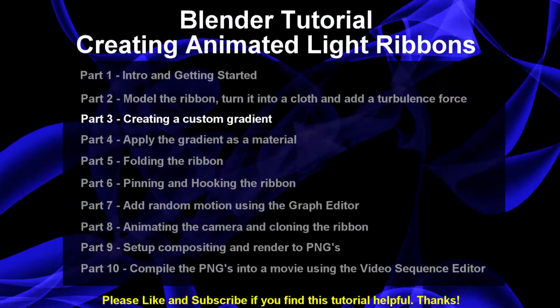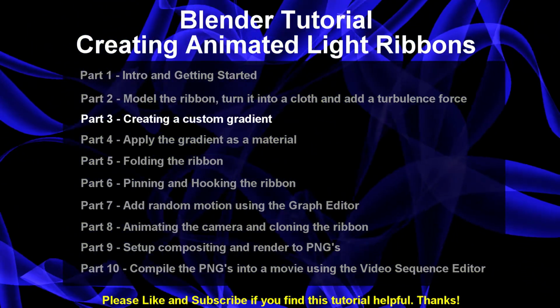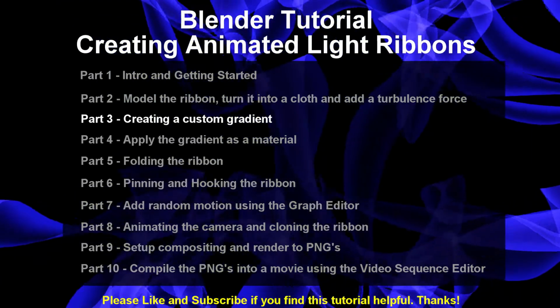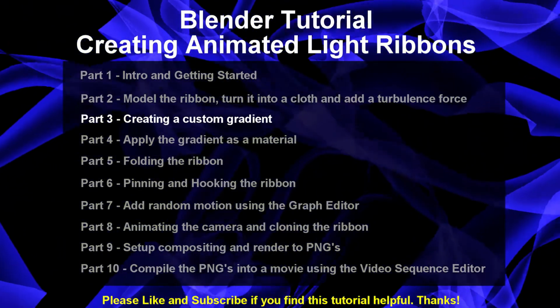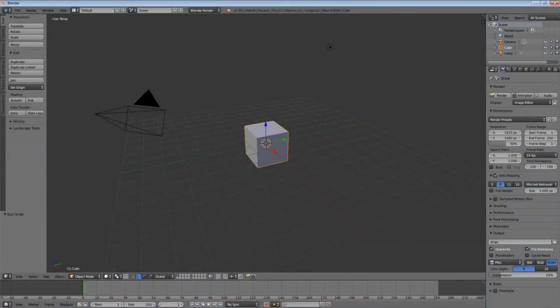Hello and welcome to part 3 on how to create animated light ribbons using Blender. In this part we're going to create our own gradient texture to apply to our ribbon. The texture will be used to make the edges of the ribbon glow brighter, with the center being dimmer and more transparent. Start by launching a new instance of Blender, and select Cycles Render from the drop-down.